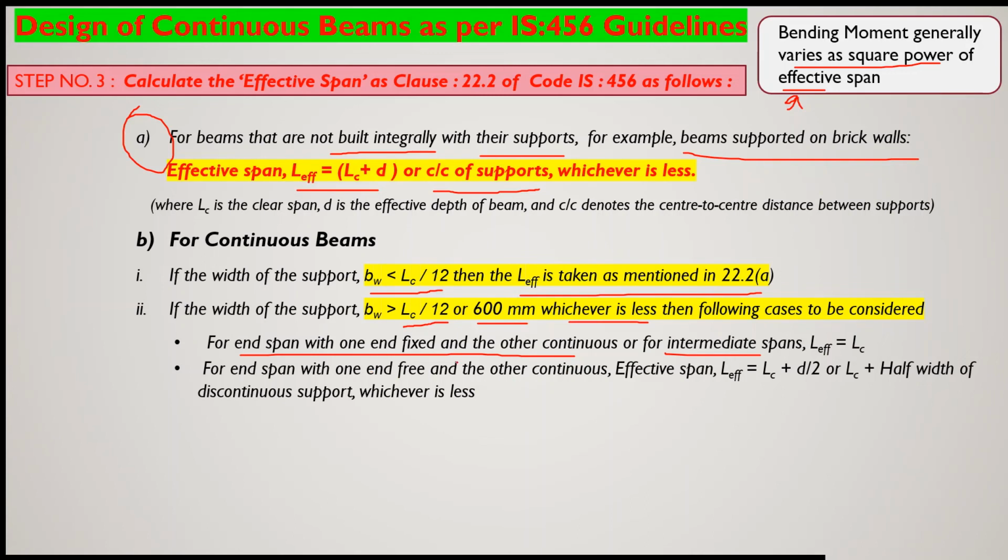Now first of all try to understand. Suppose you have to design a continuous beam of 3 span length. 3 spans mean there will be 4 supports. So on one side there will be an end span, on the other side there will be an end span, and in between the spans will be known as intermediate spans. So if you are going to design the beam for the end span at the extreme end, it may be left end or right end, where one end is fixed and the other end is continuous, or you have to design for an intermediate span, then L effective can be taken as equal to LC, that is clear span. So this is clear.